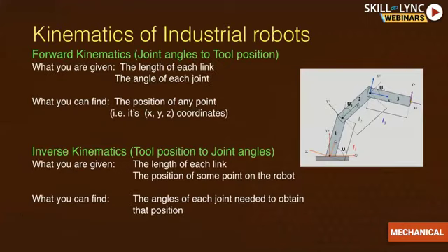So let me give a little bit of technicality. I don't want to scare you all by giving more technical details. How do we control this robotic arm? Of course, kinematics is involved. Dynamics also is involved. So the first thing you need to study when you're making an industrial robot is the kinematics aspect. Each robot has something called an arm equation, which you need to frame, which is nothing but a matrix made by multiplying a lot of rotation matrices. You have something called a frame.